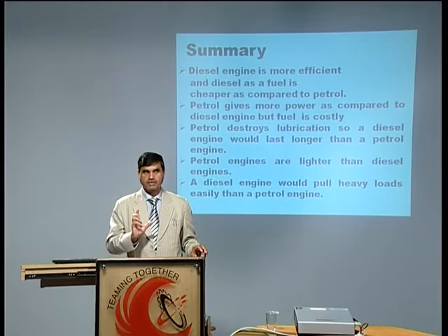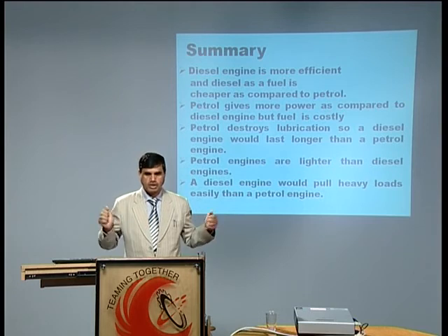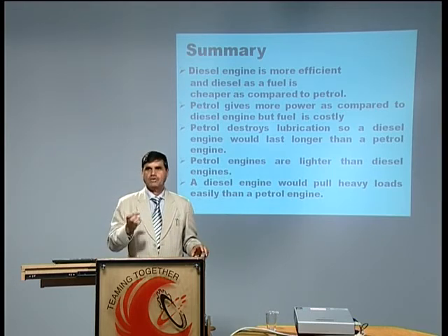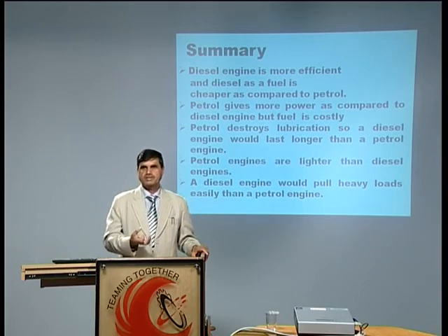More power they are giving with same size because combustion is very rapid. Very rapidly they are giving the power. So their power output from a given size engine, in the case of petrol engine, is much more as compared to this one. Petrol engine can destroy lubrication, I said, because temperatures are higher, lubricating oil can burn in cylinder itself.